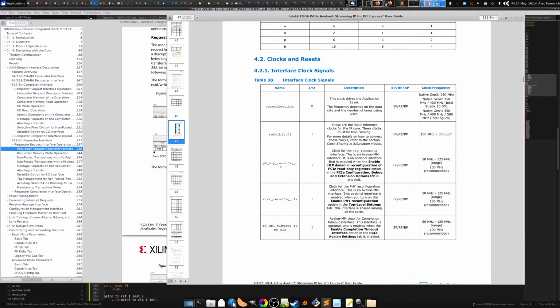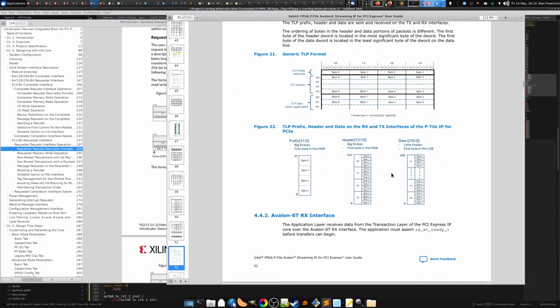The other advantage to doing this is maybe a little bit clearer from some of these pictures, is that they actually have different endianness on these different interfaces. And at first I'm like, why are you doing that? But then I realized that actually PCI Express, the headers are big endian, and it's always easier to deal with data in little endian. So with this setup, you can keep the data in little endian, which makes things much easier for dealing with in the core logic. But then the headers are transferred in big endian, so everything always lines up the same way. So in this case, when you change the size of the header, well, the header always starts here, and then it's either a question of whether you have this, you know, last D word containing the rest of the header. So, you know, it's not too bad.